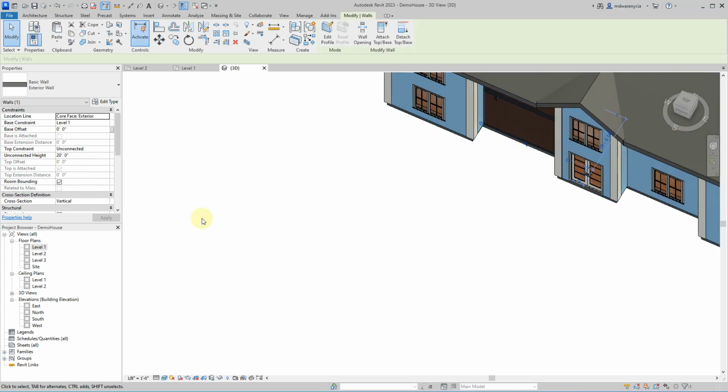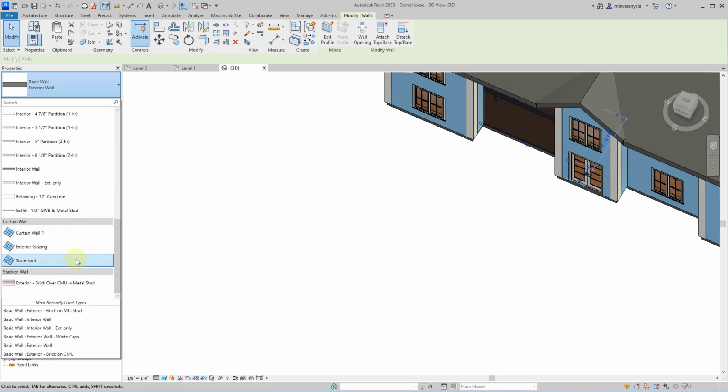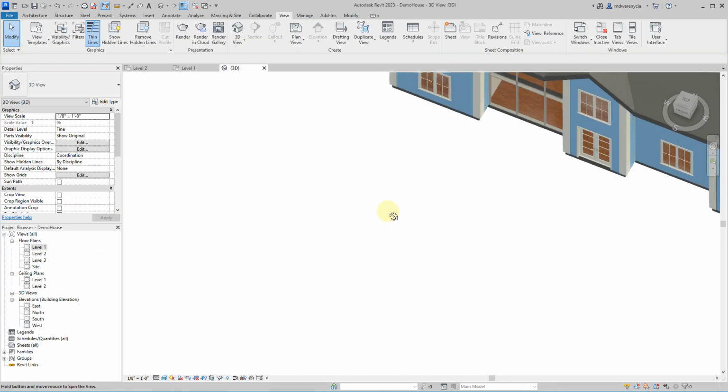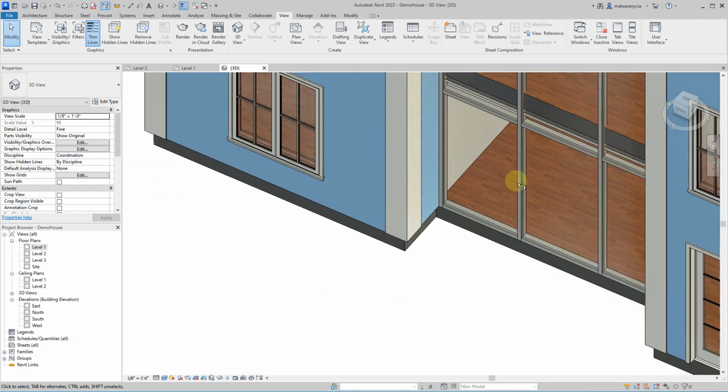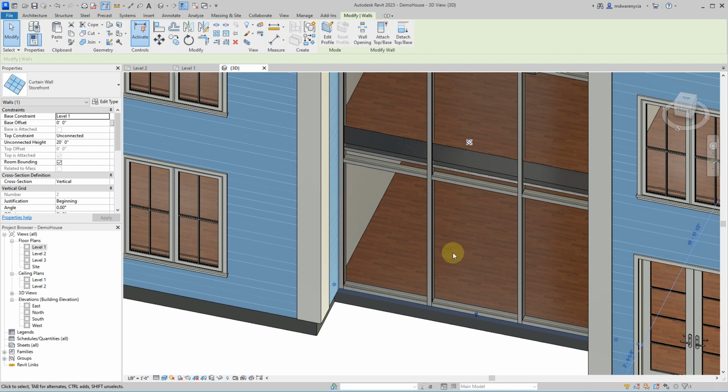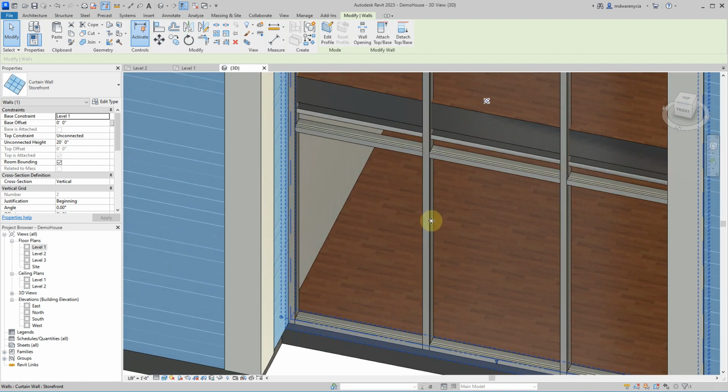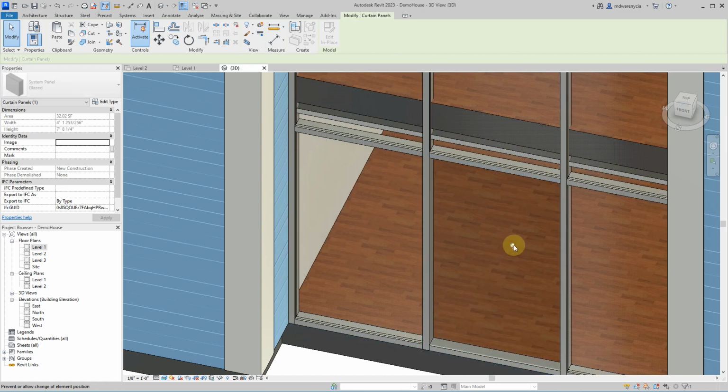Some of you have been shown the storefront windows here, and so I might as well include this in the video. When you're messing with storefront, this is an example of where you'll find something that's locked by Revit by default. Right here, there's this window, and I've shown you guys you can hit tab and it'll cycle through elements. You can see that I hit tab twice and it highlighted this window pane. If I click on it, you can see that it's locked right here, and if I hover it, it says prevent or allow change of element.